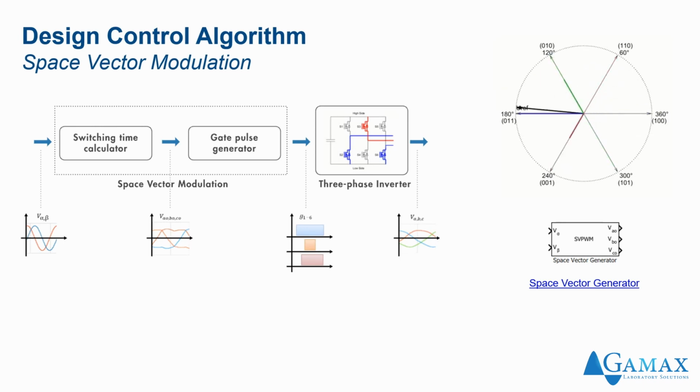The objective and the goal of the space vector modulation technique is to generate the switching sequences that correspond to the reference voltage vector for every PWM period to achieve a continuously rotating space vector. It takes the reference voltages created by the inverse Park transform and generates the duty cycles to be sent to the PWM driver on the microcontroller. So the PWM driver outputs the required pulse width modulated signals to the three-phase inverter, which then generates the desired three-phase voltages to the motor.